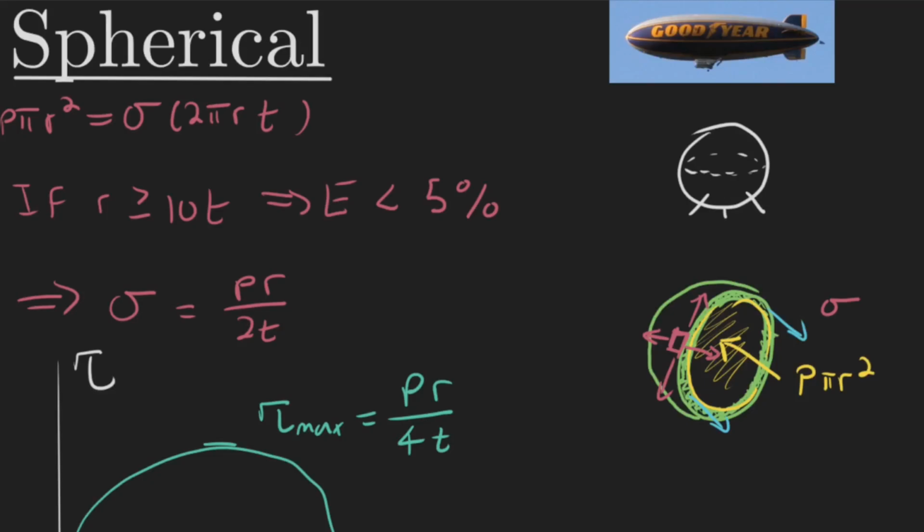The only other thing I would say is that there is a difference between whether you're on the outside or the inside of the sphere. So if you're on the outside, we're saying that there's no radial pressure because the pressure that we're putting in here is what's called the gauge pressure, which means it's relative to the outside pressure. So basically, we're going to let the outside pressure be 0, and then this P right here is equal to the difference in pressure from the inside to the outside. So, right? If I'm looking at an element on the outside going into here, I would have 0 pressure.